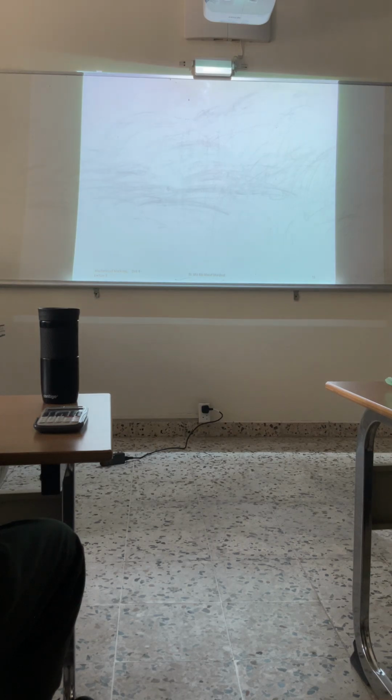What are the methodologies? Give me different methods to achieve the static balance. Yes, go ahead, Khaled. By adding a mass. Mass where? The opposite of the mass which causes the unbalance. Yes. The second method? Removing material. Removing material from the opposite side or from the same side? Opposite side? Are you sure? From the same side. Same side of the centrifugal force, the unbalanced masses.